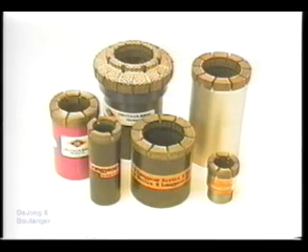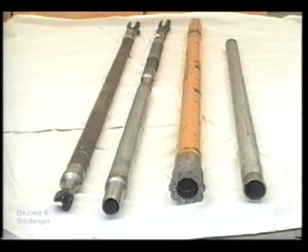Diamond bits are the most versatile since they can produce high-quality cores in materials ranging from hard or very dense soil to hard rock. As shown, coring bits come in a variety of shapes and sizes, each of which is suited for a specific situation. Some systems, such as the Christensen 94 pictured here, can perform multiple tasks such as drilling, coring, and sampling.